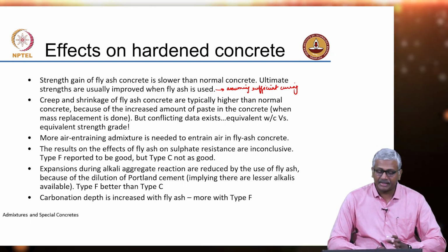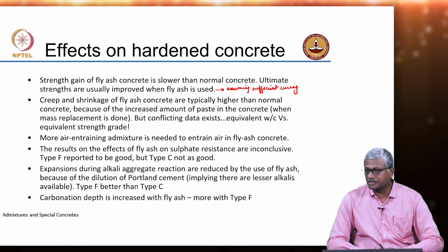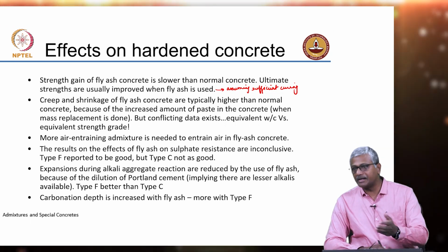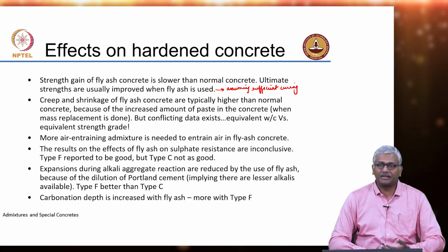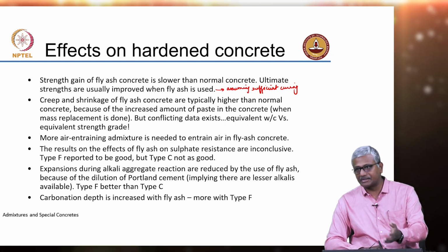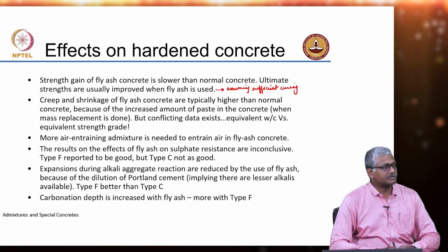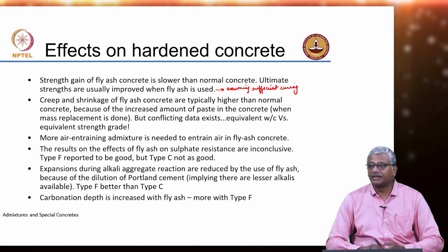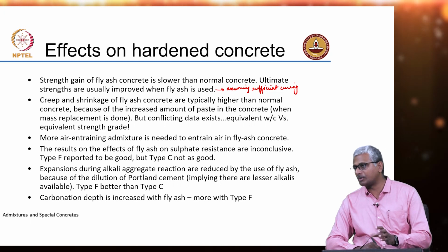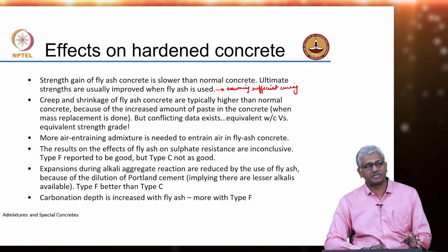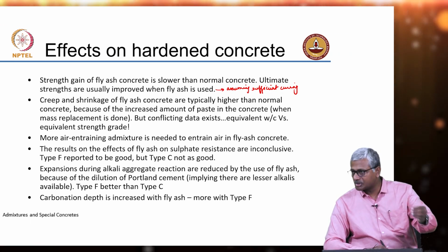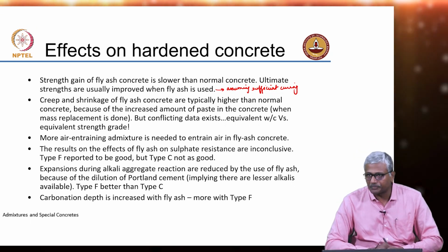Creep and shrinkage, again as I said, there is conflicting data. We expect that because powder volume is increasing or paste volume is increasing, we have a greater tendency for shrinkage or creep. However, data from research seems to have conflicting information. Some research says that yes, shrinkage increased, and some other research seems to indicate that there is not much difference, or even a better performance is seen when fly ash is used as a cement replacement. But again, you will have to be very careful about these papers where all such information is presented. You need to go into the details of how they have calculated shrinkage, how they have actually done the measurement, how they have done the mix design also is very important for you to consider.